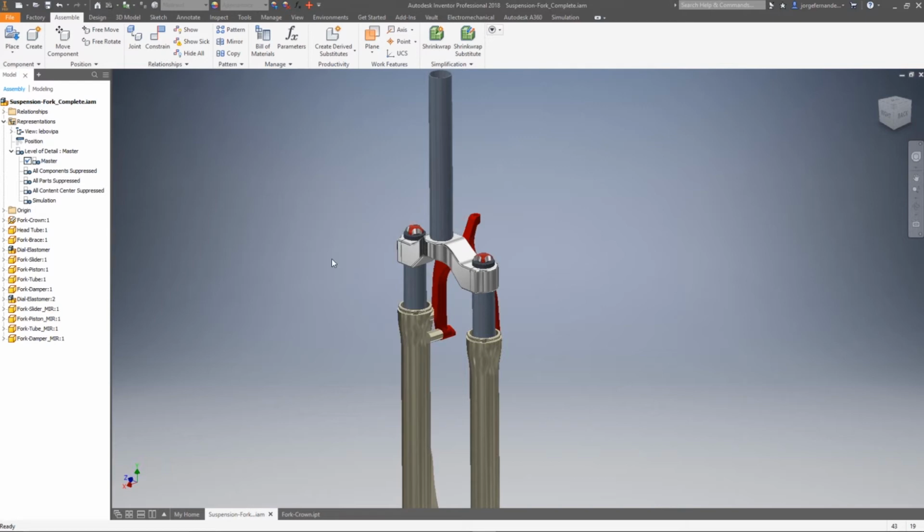Right now, we'll keep it straightforward at the one part, but we could come in here and use contacts and make sure that everything's set up with this sub-assembly or more if we wanted to. Sometimes, again, if you just want to get a rough idea, it's good to open up the part, apply it, and see what works. We would still be able to use levels of details inside of Inventor here to exclude everything else in just the one part.